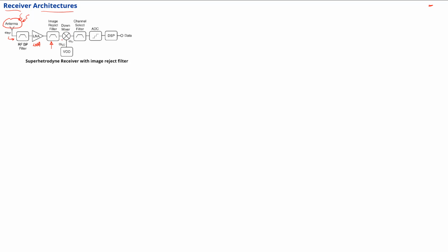what a mixer does, essentially to have a pure shifted version, a frequency translated version of the RF signal that is picked up by the antenna, beyond the mixer, but shifted to a frequency called the intermediate frequency. So essentially there is a local oscillator LO, and the IF frequency FIF is going to be FRF minus FLO, the local oscillator frequency. And this frequency being much lower, the requirements for digital sampling are going to be lower as well. That means it can be sampled at a lower sampling frequency.